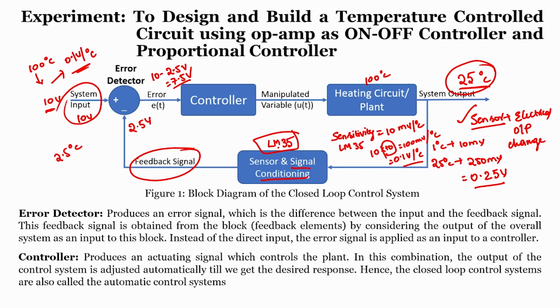If you go with an instrumentation amplifier, it may be a little higher cost, but the input impedance and the CMRR will be really good. But if you go with a difference amplifier, even then that is more than enough for us in this application, since the signals we are getting are not almost a common signal. So, it is more than enough for us to go with a simple differential amplifier rather than a 3 op-amp based instrumentation amplifier or any kind of instrumentation amplifier in this application.